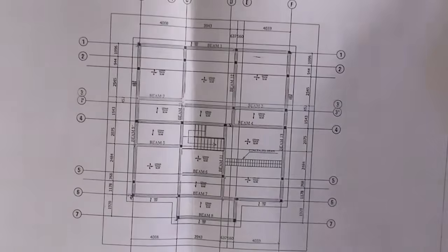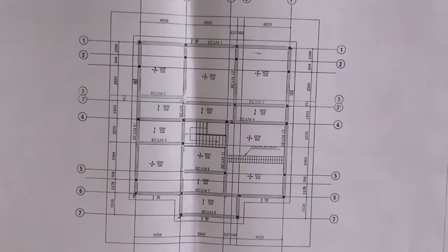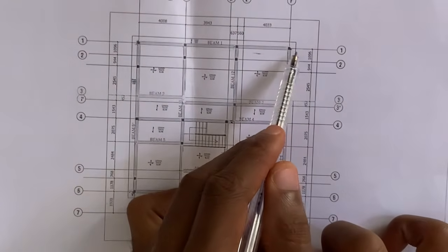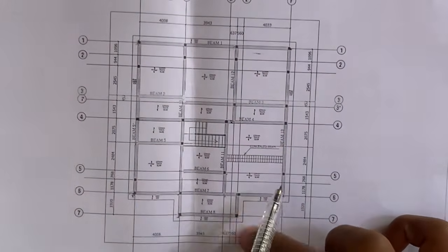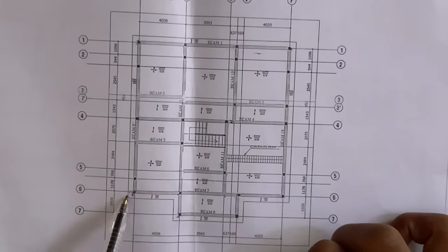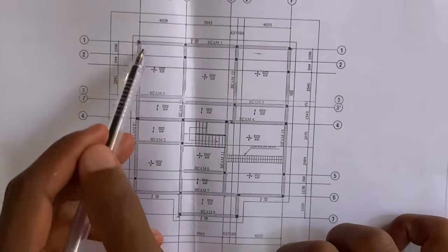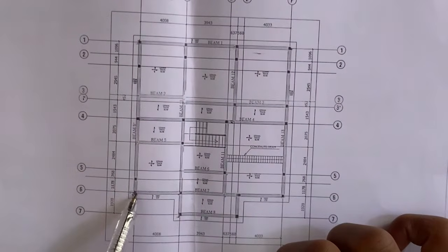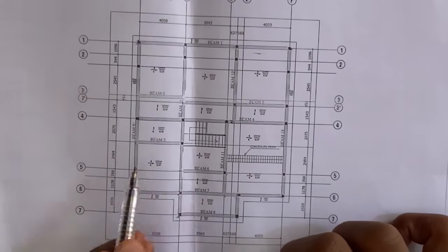So now the next perimeter or the next beam we're going to be looking for would be beam 9. Now remember that we catered for beam 1 and beam 7 to be out to out. So now beam 9 is a vertical beam, which is this beam here. So how are we going to be measuring this vertical beam? It will be in to in. Why?